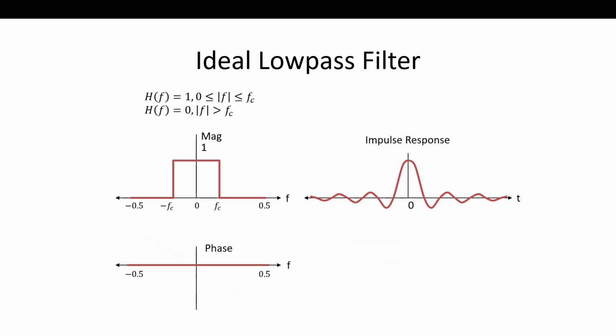That's why if it was zero phase like this, it's zero delay. And that's what you're seeing in frequency: this rectangular pulse, a brick wall filter. And just to commit it to memory if you haven't yet, the Fourier transform relationship between a rectangular pulse in one domain is a sinc function in the other domain. You just see it so many times, in so many places. If I stopped you on the street somewhere and asked you, you'd know it like that. So that's what we see on the right: the sinc function as the impulse response.